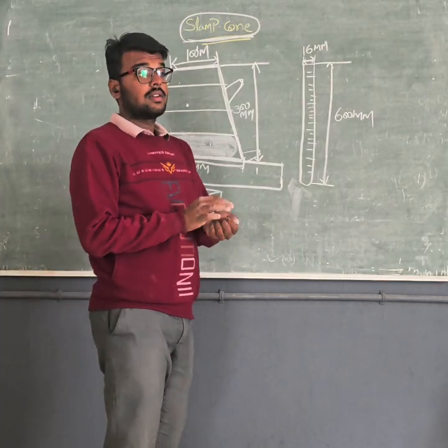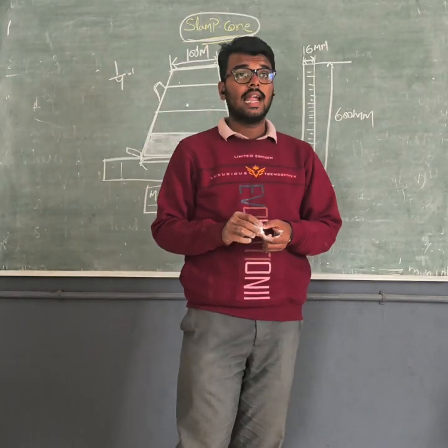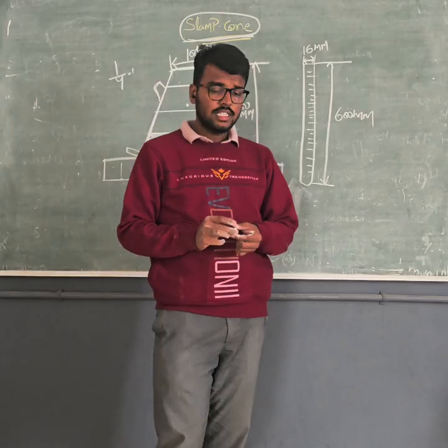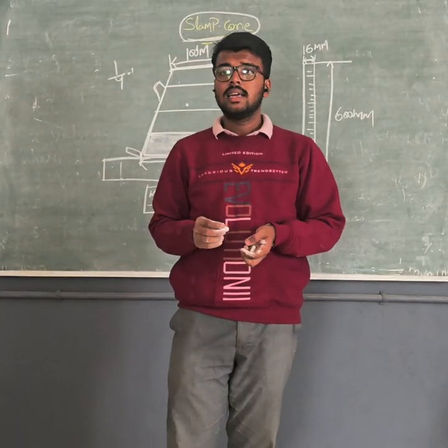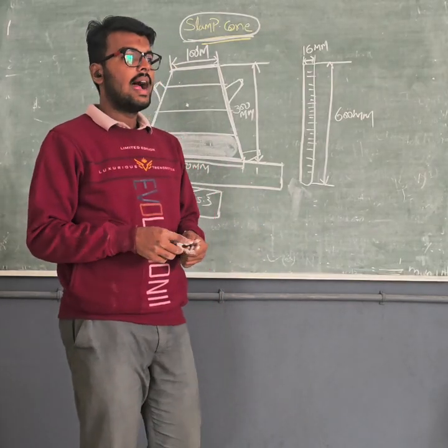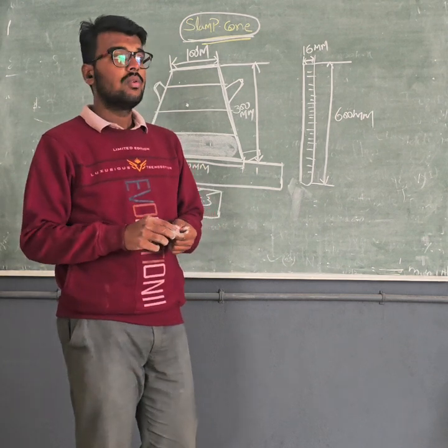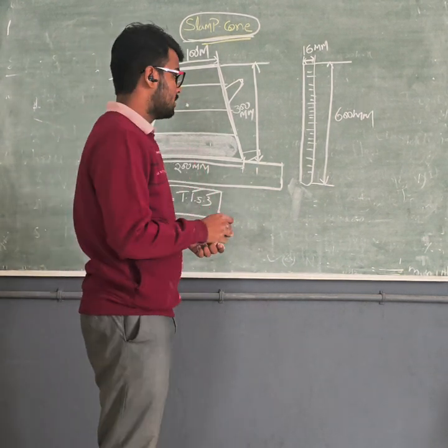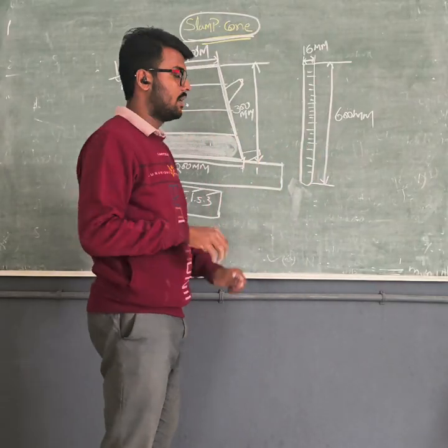What is the condition of this concrete? If the concrete is in segregation criteria, what is segregation? Segregation is a phenomenon by which the finer particles of the concrete separate from the coarse particles of the concrete. And bleeding is a concept where, after casting, we find some water content shown in the topmost part of the concrete level.